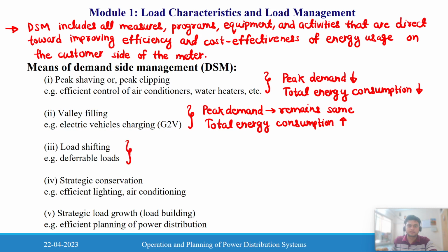And for load shifting, we keep the total energy consumption the same and reduce the peak demand. Whatever demand occurs at on-peak hours, we shift it to off-peak hours.